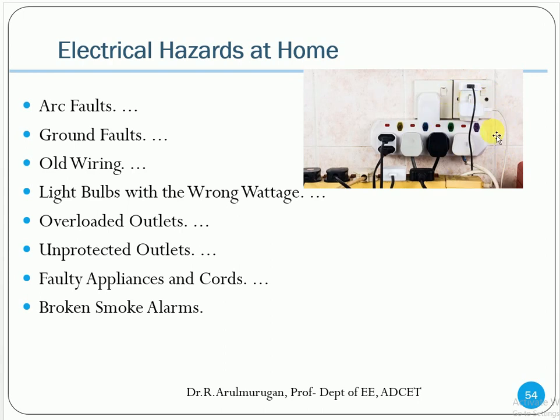This is about the switchboard. Many sockets are connected to the switchboard. A switchboard costs around 50 rupees, but each socket carries a load of many amps. Because the cost is very low, the wire used is very thin, 1 square mm. But here you are using around 10 amps. If you add it up, this wire cannot withstand it and will melt inside.